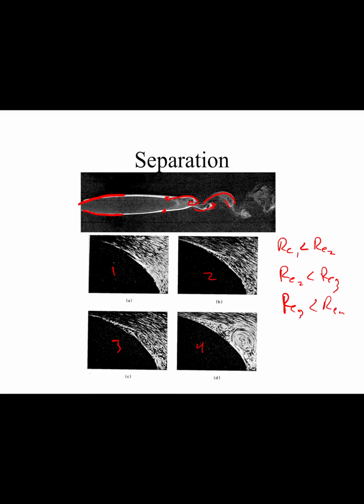As we increase this Reynolds number, we can see that separation starts to occur at points that move upstream, and then these reverse flows occur. So we have a clear reverse flow associated with these eddies that are there. This is the region of reversed flow after separation occurs. This is really an important concept. Even over these objects, sometimes you'll have reattachment.